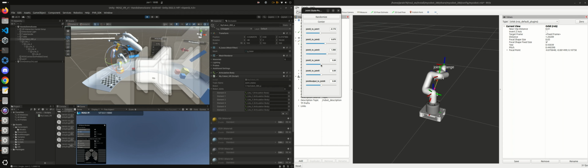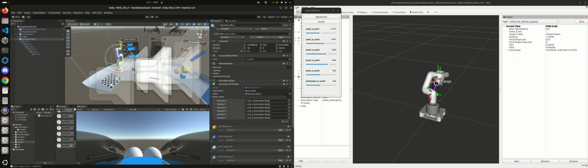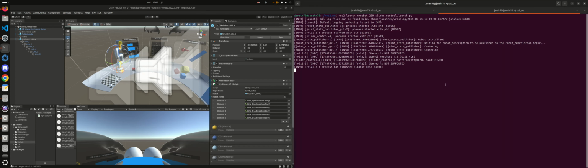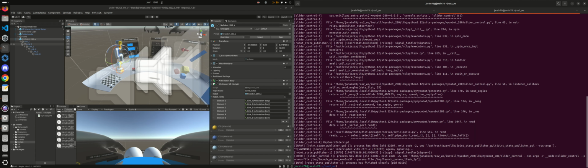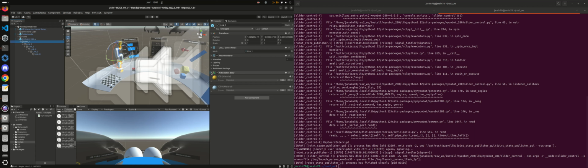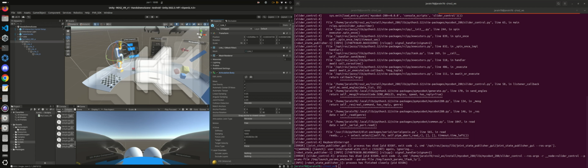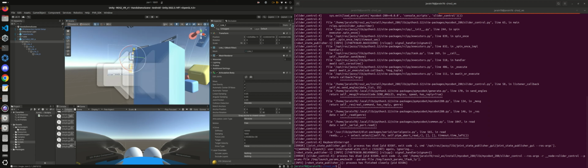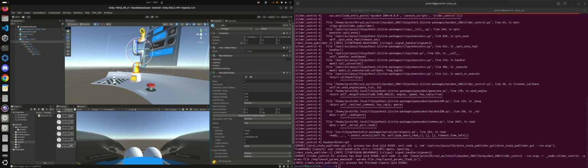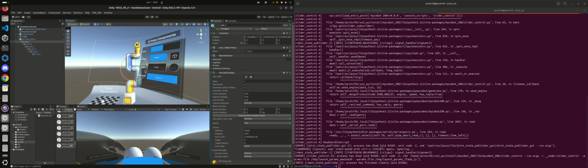Basically, it's because the articulation, the joint, is not in the center of this joint. How can we solve this? Sometimes it's simple to solve, but sometimes not. We have two options: return to Blender and modify the articulation in Blender, or use these tools. This is the base. This is the movable. This is link 1.